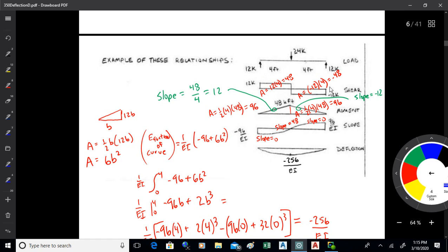Apply those same set of rules again to get from the shear to the moment. You can just keep applying those rules here. So you can look at the area under the moment diagram here. That'll be the change in slope. If you realize that when you load a beam up, you start with a pretty extreme negative slope, then this area will be positive. That'll increase the shear, something like that, the slope something like that. Then you'll get still a positive area here, but it will be increasing at a decreasing rate, so that'll flatten out. So you'll get to a slope diagram like that.